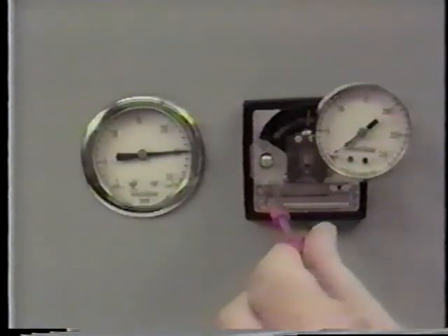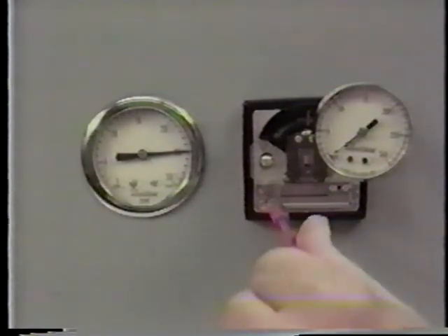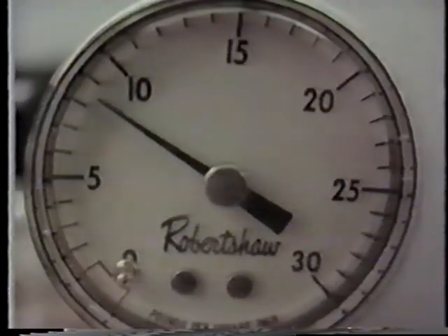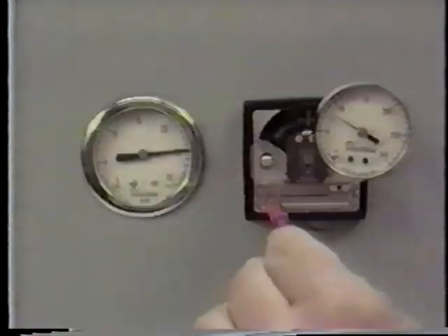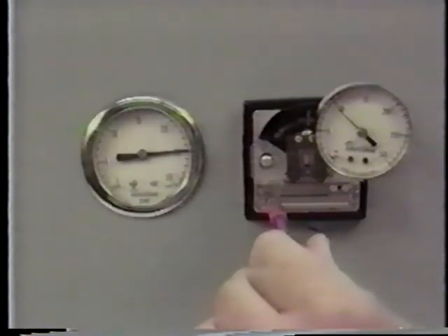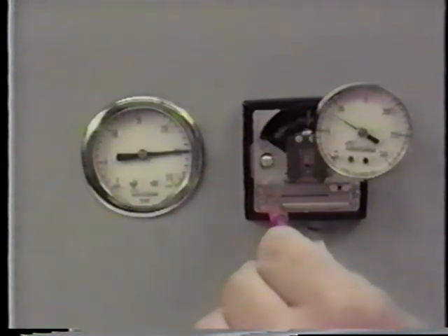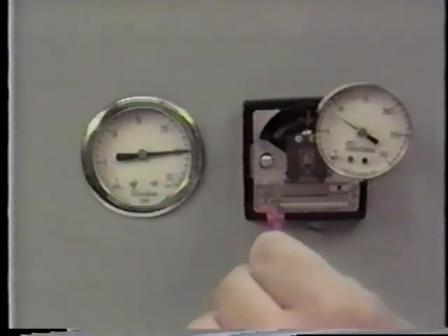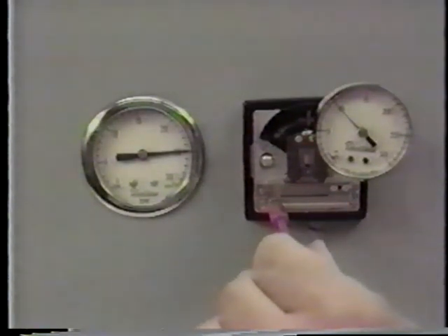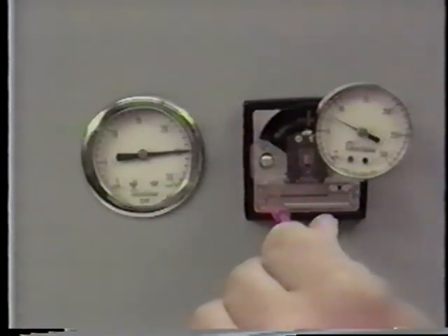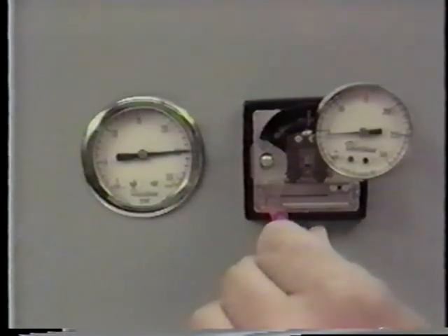Continue rotating the screw in the scale a small amount, then turn the screw back to read 9 psig. Read the scale. It should read ambient temperature within 1 degree Fahrenheit. It may take a few tries to accomplish this calibration. Using the calibration wrench, rotate the calibration screw until the dial indicates the desired night cycle set point.